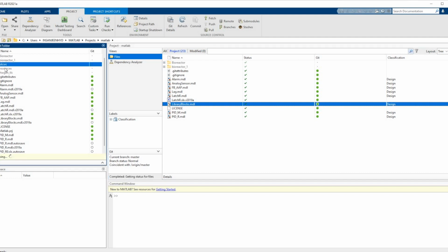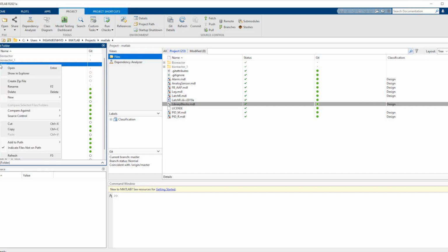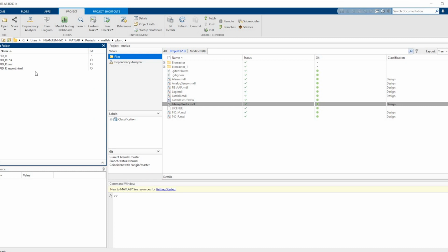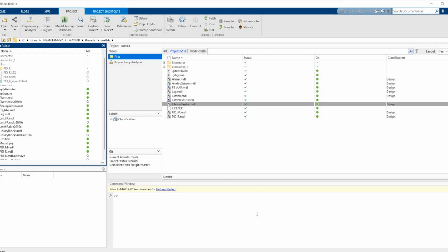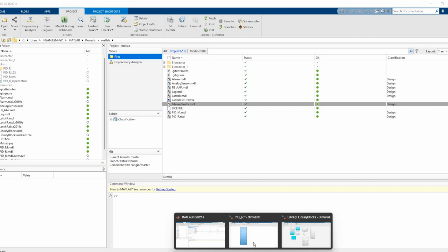So we can see that in the PLC SRC folder, the blocks will be generated and shown here. .L5X is for Rockwell, and .xml is for Codesys, PLCopen XML, TwinCAT, or Phoenix, because all support the .xml format. So any of these formats will come, and here we can see that it has already been generated.